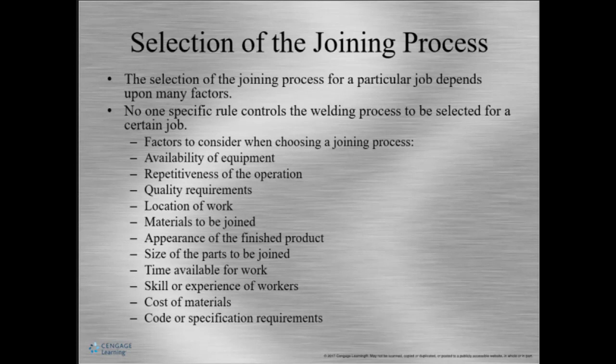So what is the availability of the welding process, the type of welding? Do I have the machine already? Or if not, is it too costly to purchase the machine? Will I have to repeat the weld several times, or is this just one weld?